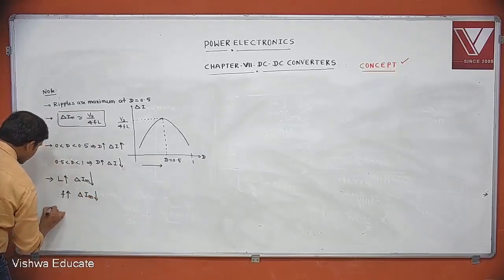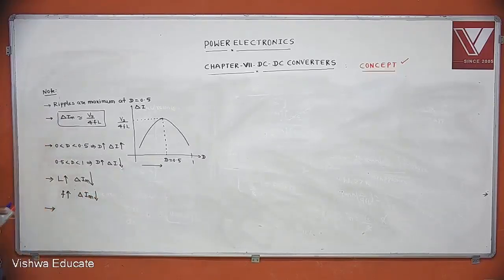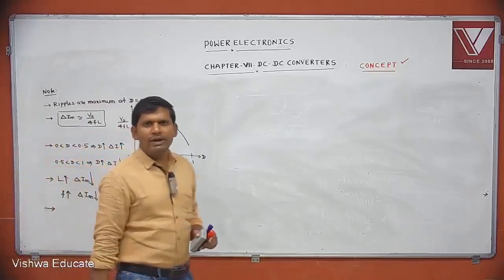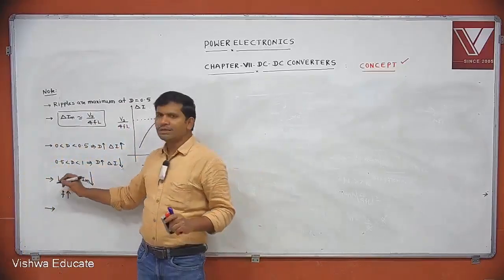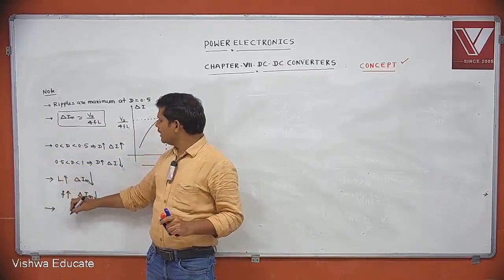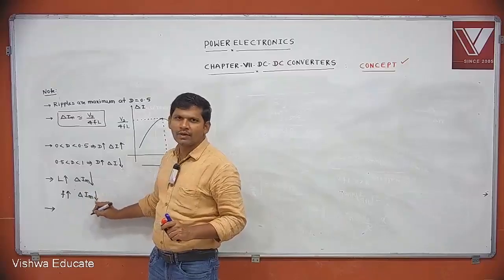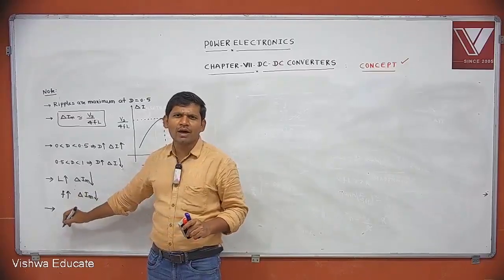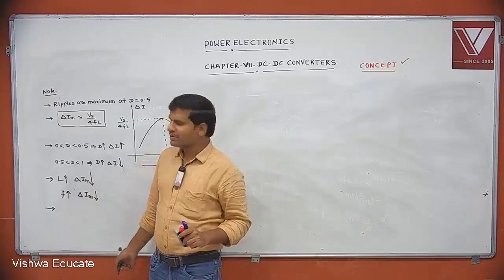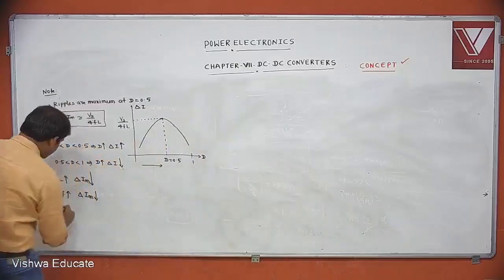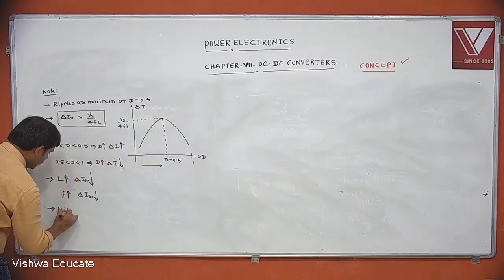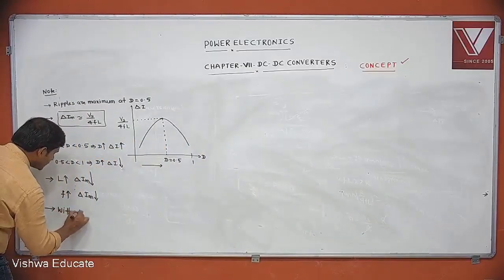Hence, without increasing inductance, in order to reduce the ripples in the load current, we must operate the chopper at a high frequency.